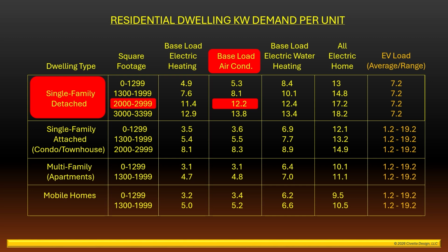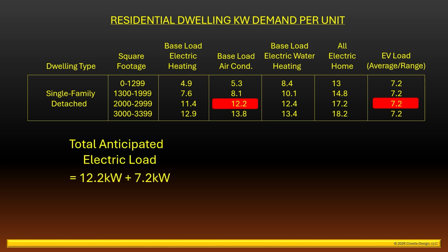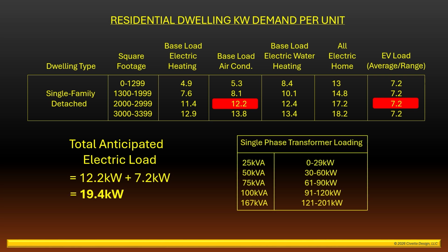Let's also assume the family doesn't currently own an electric vehicle. Without knowing exactly what type of charger would be required, should they purchase one in the future, we'll use the recommended estimate of 7.2 kilowatts. So the total anticipated electric load is simply 12.2 kilowatts plus 7.2 kilowatts for a total of 19.4. That brings us to another chart.